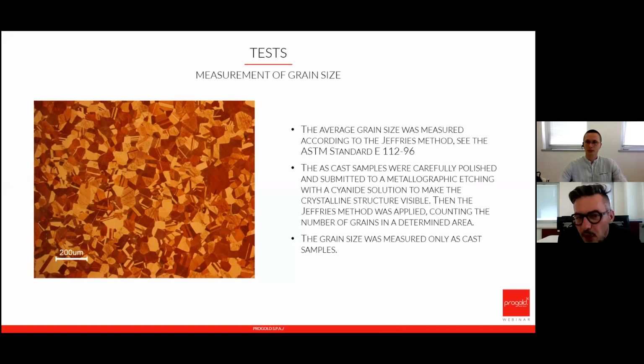Okay, and talking about form filling, which looks to be a complicated problem: if I understand well, the form filling property of yellow gold is usually higher than pink gold. Is there a way to overcome this and play with some composition changes? I think the meaning is getting the properties in pink gold that we are able to get in yellow gold. Yep. For sure, there are some elements that decrease the viscosity of the alloy, but as we said along this presentation,